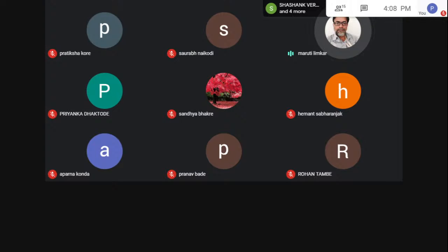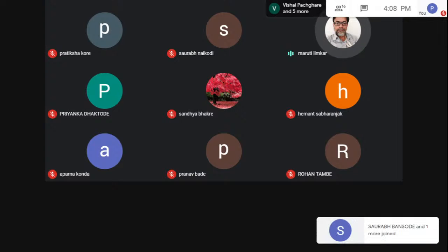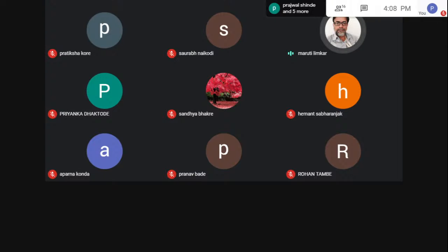So this is a DC supply. These are the four switches, these are the IGBTs. During the positive half, that is the first period, this IGBT and this IGBT will be on. At that time, current is flowing in this fashion, from this to this. Then this and this will be on, and current flows in the opposite fashion. So the output voltage is both positive and negative.